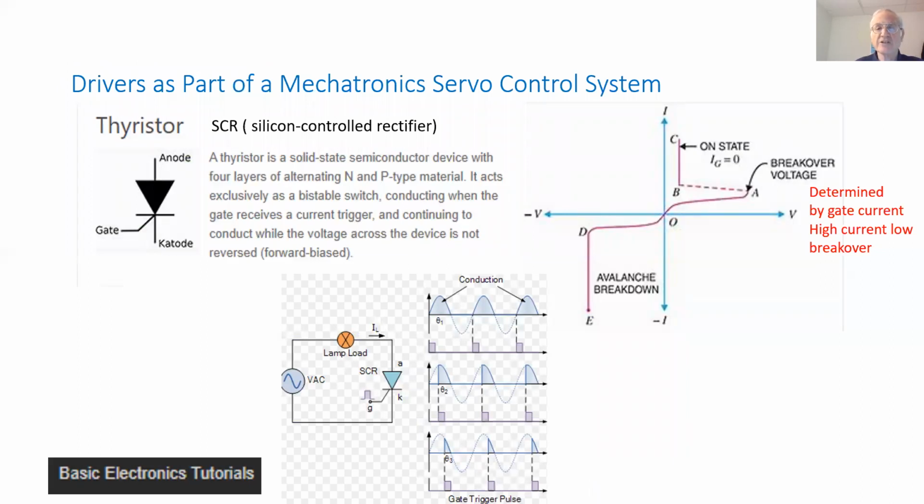The drivers are being driven by logic circuits and various mechatronics electrical components. We see over here the thyristor, or so-called silicon controlled rectifier, SCR. A typical curve is shown over here, similar to the diode. However, we have a gate, and the gate current is controlling the breakover voltage.